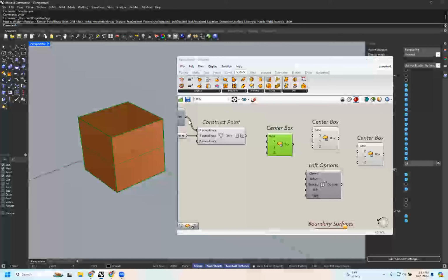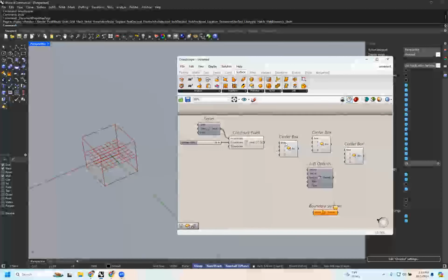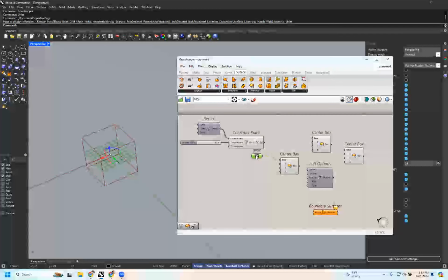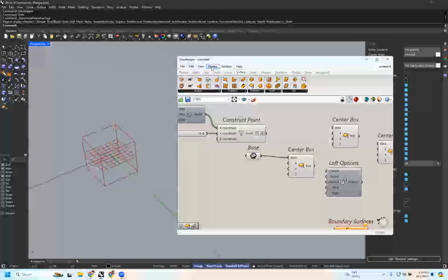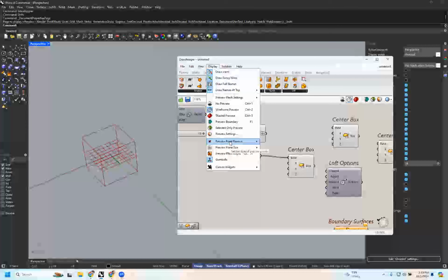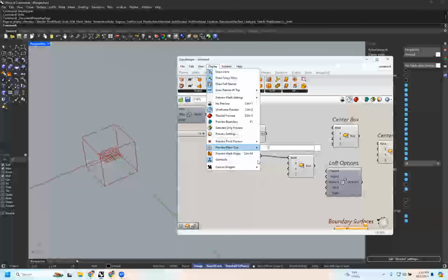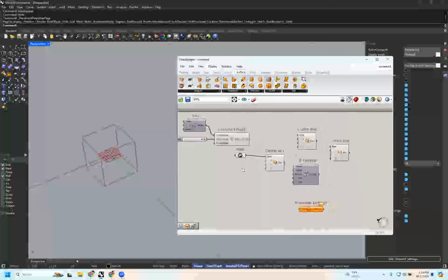So you'll notice here, I go make this wireframe. It's showing our base plane. So I could extract that parameter. That display is available to change. So when you change units, sometimes a 2-foot preview plane is a little much, and you'd want to turn that down to 1, for instance. You could have the same thing with the points and all that.